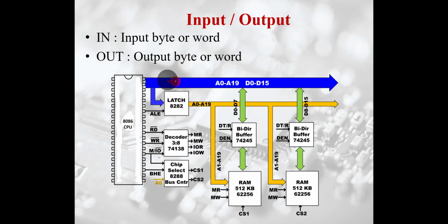First I place a 20 bit memory address here, and the latch is activated from the ALE. So now this address is latched out here, right? In case I want data from a memory, I have this memory signal going high, and then based on the least significant bit, the address is also given here.